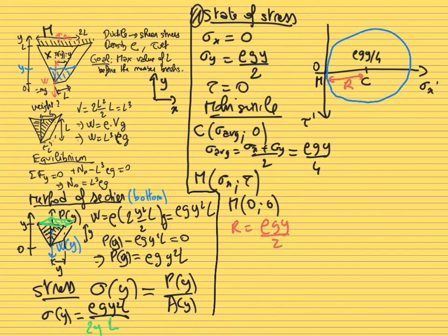In this case, the Mohr circle quickly tells you the maximum value of the shear stress. You have two possible values: the point where the shear stress is maximum or where it is minimum. In this case, the sign doesn't matter. The value of the shear stress is always equal to the radius, so it's plus the radius or minus the radius of the circle. This is a result that is always true.